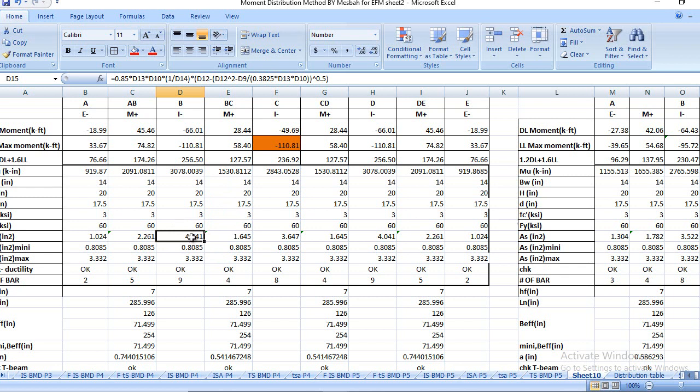So let's say I check this one is 12 and this one is 24. Clear? You see the steel area is changed now. It is decreased from that value, and this value is fixed 21.5, and they are using f'c of 4 ksi. So you see 2.948. This is the beauty of this calculation.